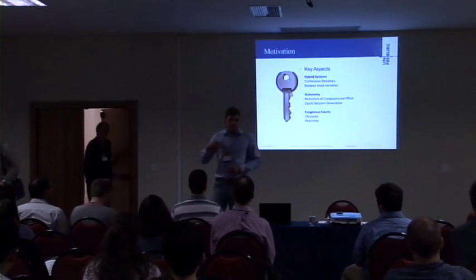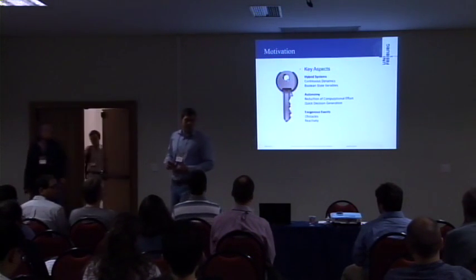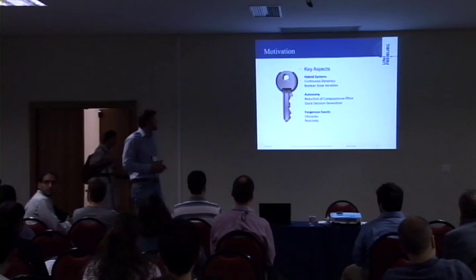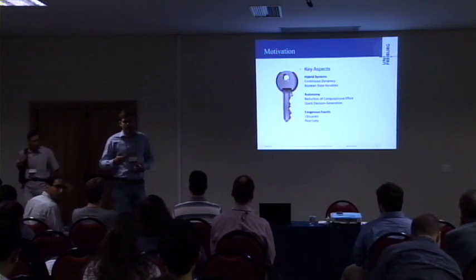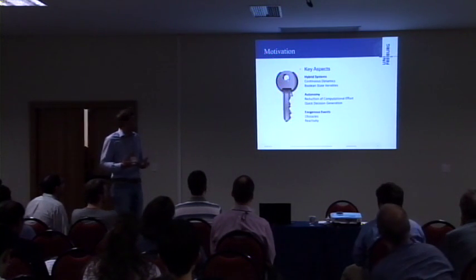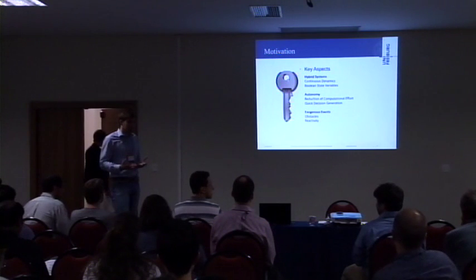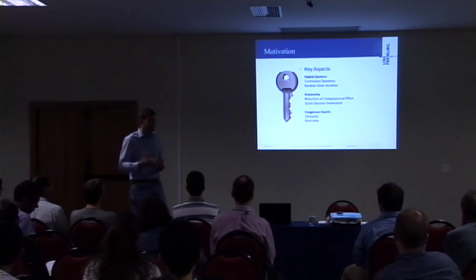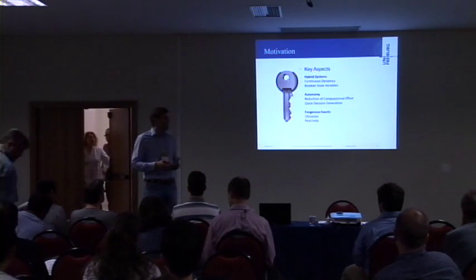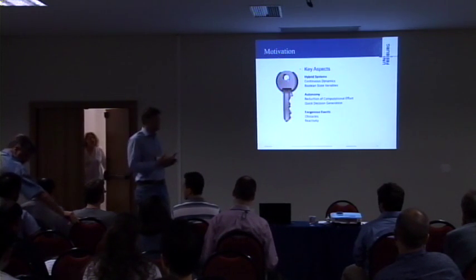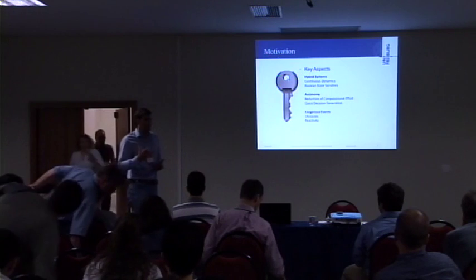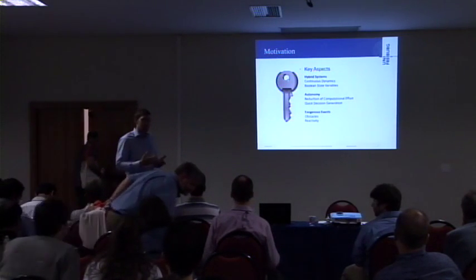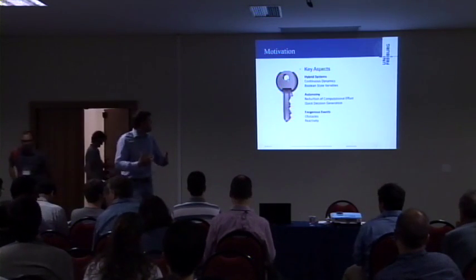And if we want to develop such a framework, we have to focus on 3 main aspects here. First of all, we have to handle a hybrid system. That basically means we have a system with continuous dynamics, which are captured by numerical state variables, and we have additional Boolean state variables, which define the mode of the hybrid system.